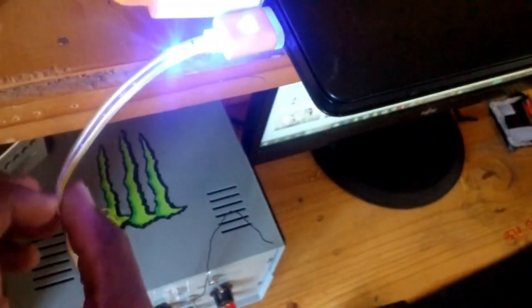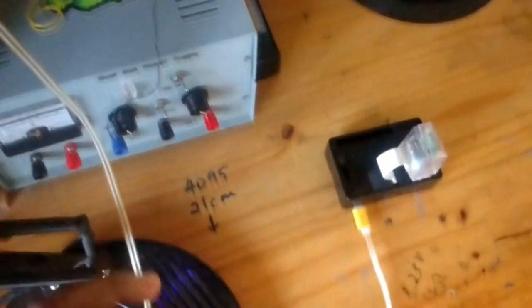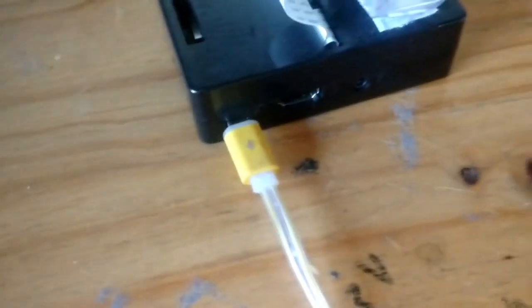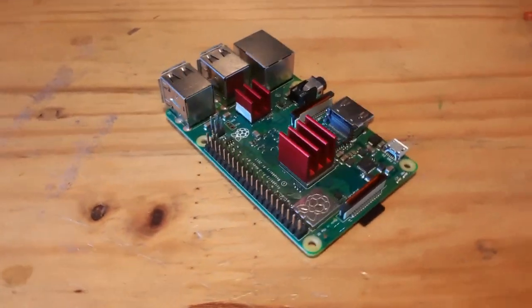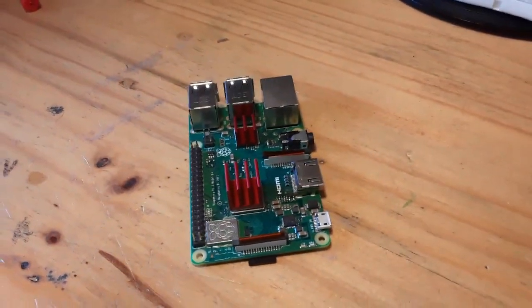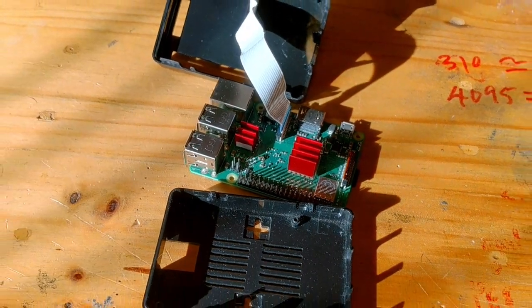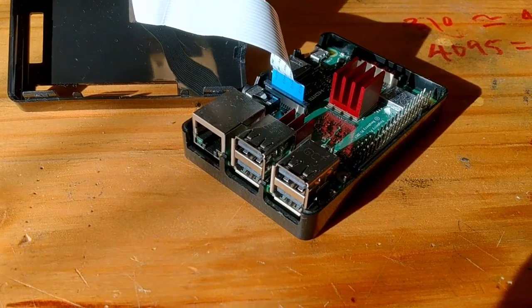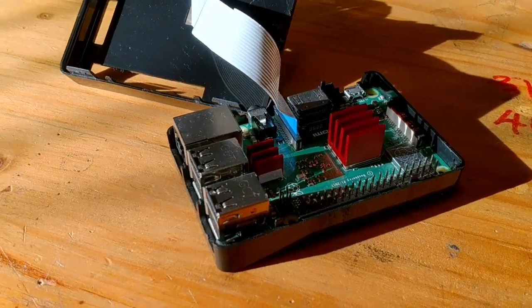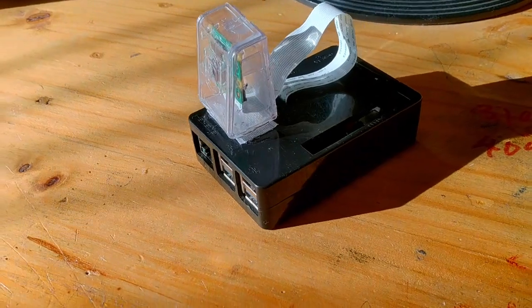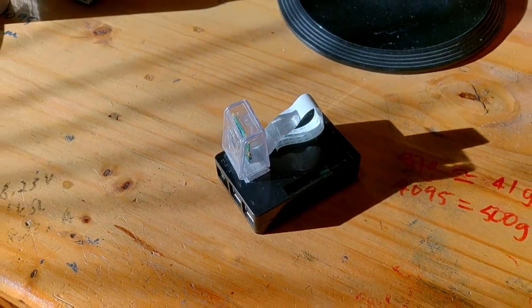You can get a max current output of 500 milliamps at 5 volts, and 900 milliamps at 5 volts for USB 3.0, the blue USB port. The Model B uses between 700 and 1000 milliamps depending on what peripherals are connected. On my daily setup, I run the Raspberry Pi over a VNC connection, thus this frees up my peripherals and I don't need much power to run as a result.